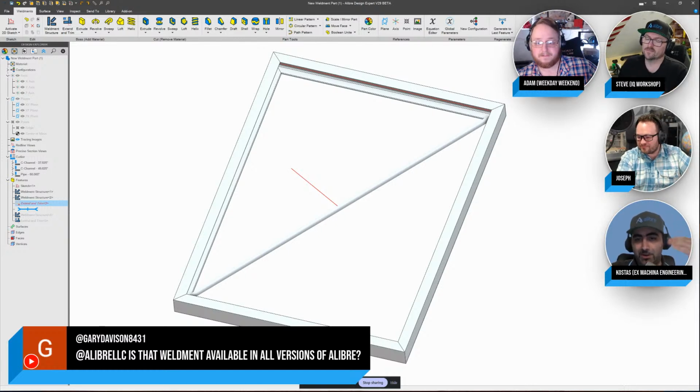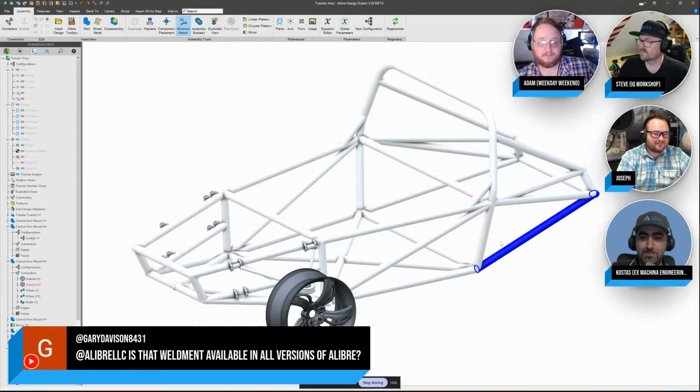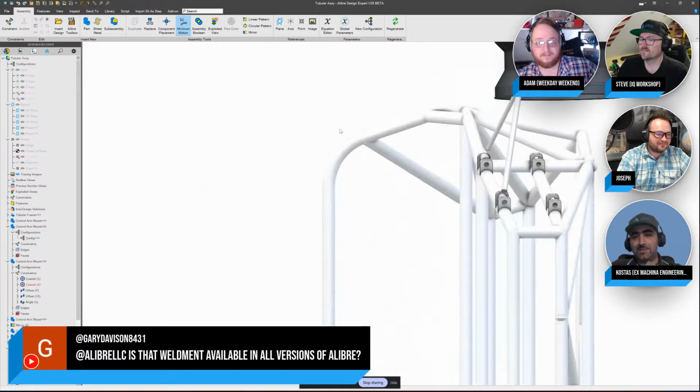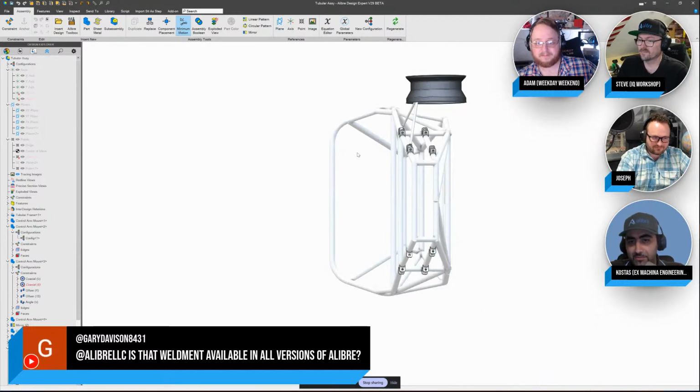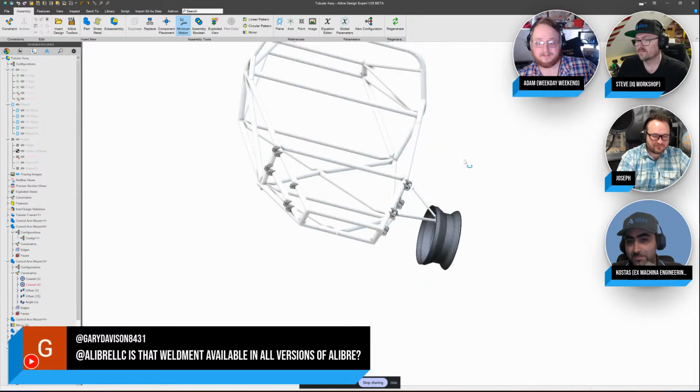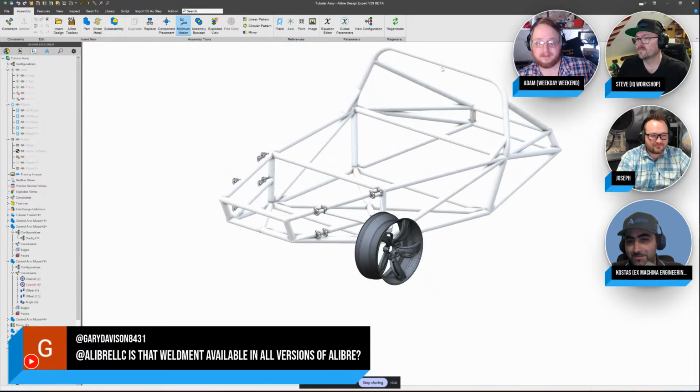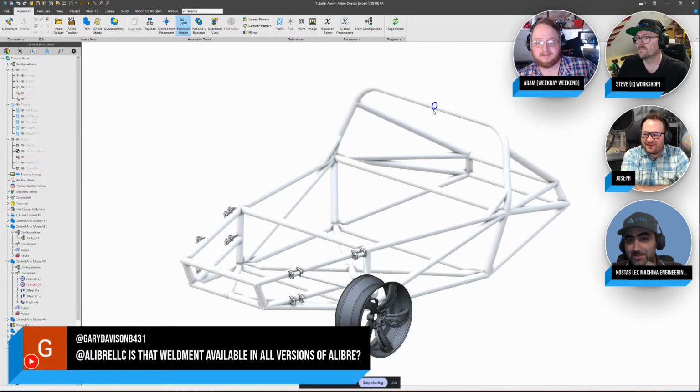First of all, that's awesome that it can do weldments with curved pipes as well. And what would be like knocking it straight out of the park is if you could get, in a drawing or in a cut list, the length of that pipe before it was bent, so you can cut it to size and then bend it.